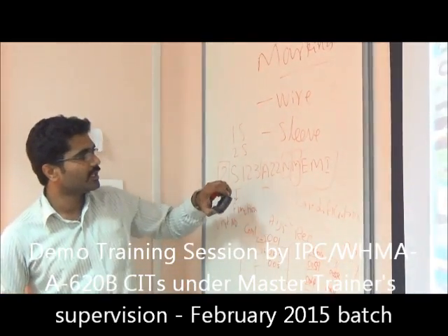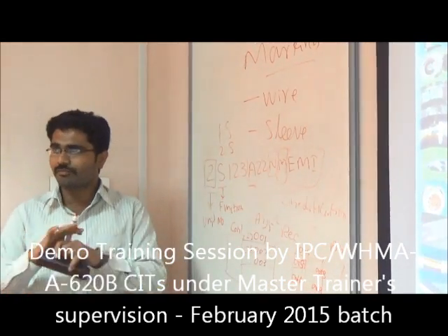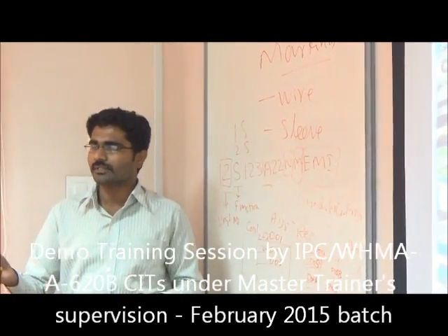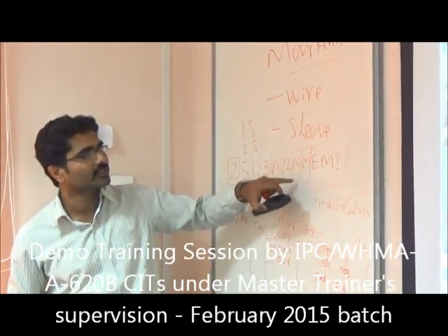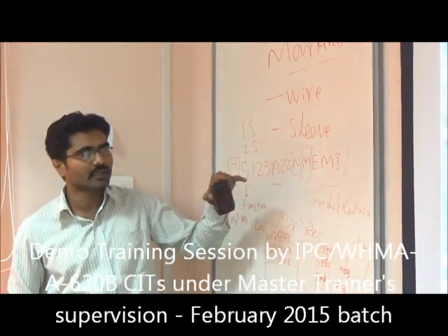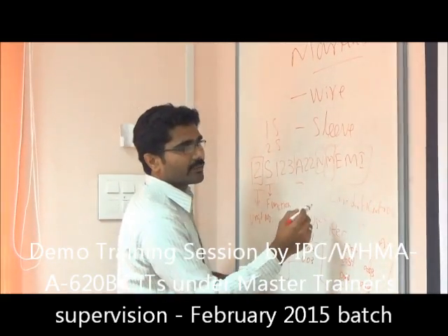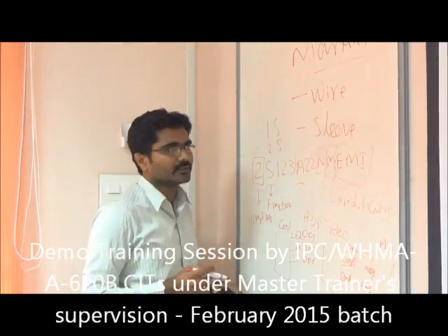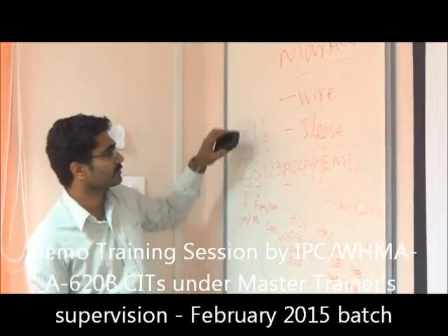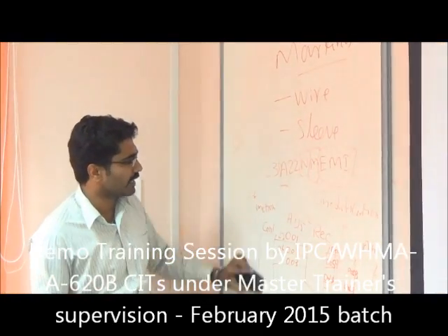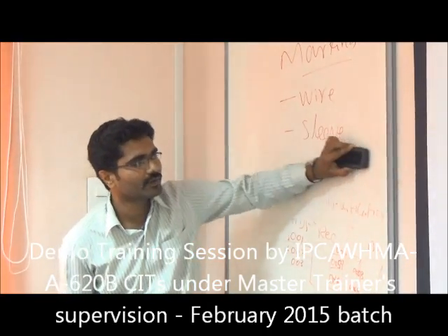Actually, if I am the OEM and I manufacture the aircraft, I won't mention this. If I fully complete the aircraft and sell it to someone else like HAL, and they want to add some more equipment, that time they will mention this. It means the aircraft is not original manufacturing; they have modified it. If it is an EMI cable, they will mention that this is the EMI cable. This is for wire identification. They will conduct this globally, and on any aircraft they usually follow it like this only.